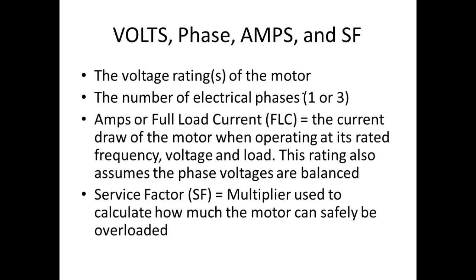Service factor is a multiplier used to calculate how much the motor can be safely overloaded over a short period of time. If it has a service factor of 1, like our motor over there, what does that mean? We can't overload that motor. We can't plug that motor either. What's plugging? When we plug a motor, what's plugging? Reversing it without it coming to a stop.